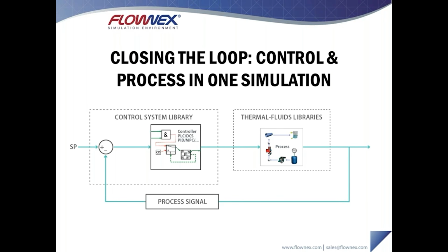All right, so to begin, a control system in a plant, be it a processing plant or perhaps a generation plant or something like that, is the nervous system of that plant. Nowadays, manual control is out of the window. People don't operate valves by hand anymore. Everything is done digitally. So the control system itself is integral to the performance of this plant. What this means is that poorly tuned control systems severely impact the performance of this plant. Oscillations in process conditions result in processes having to be turned down slightly to ensure that maximum limits are not reached. This results in reduced production and reduced efficiency of these plants as well. So properly tuning these systems can increase the efficiency, reduce your energy costs, and increase the production of your plant.